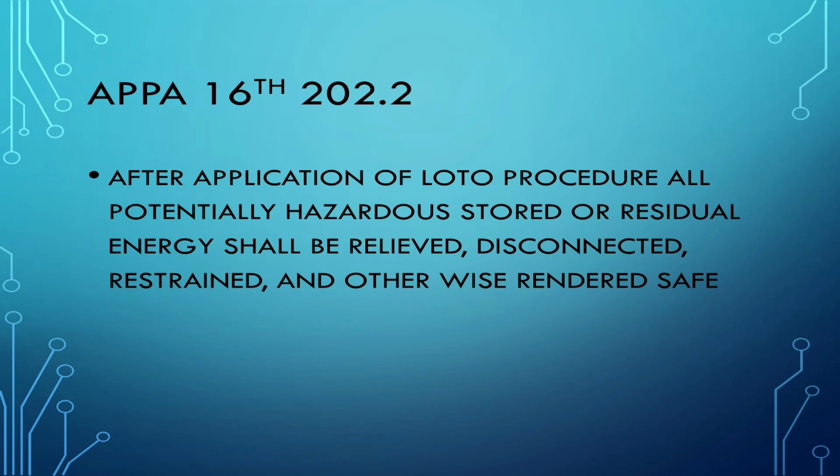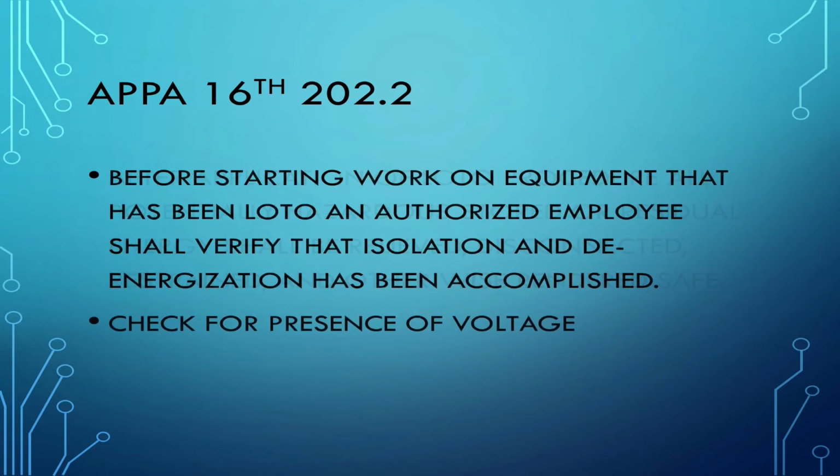After application of lockout procedure, all potentially hazardous stored or residual energy shall be relieved, disconnected, restrained, or otherwise rendered safe. Can you put a set of grounds on? Can you see the 5 minutes or 3 minutes, whatever your company procedure is, on a set of capacitors for them to be safe to handle? So know your equipment, know what you're dealing with, and don't be afraid to ask questions.